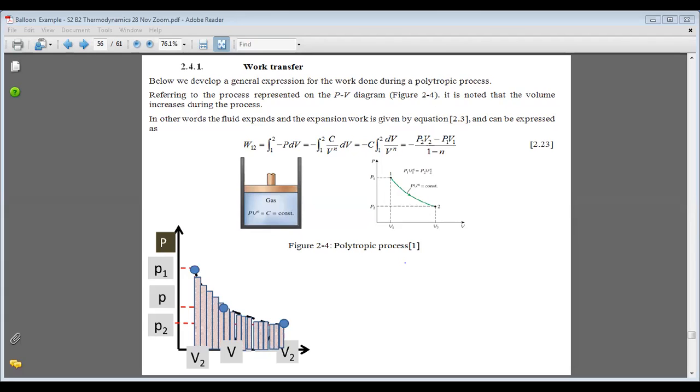Air cooled, still not maintaining as close as water cooled, but anyway the compressed air is getting a little bit stable temperature, so N equals 1.2. When stability is deviating further, that is 1.3. Okay, so it is something like this.